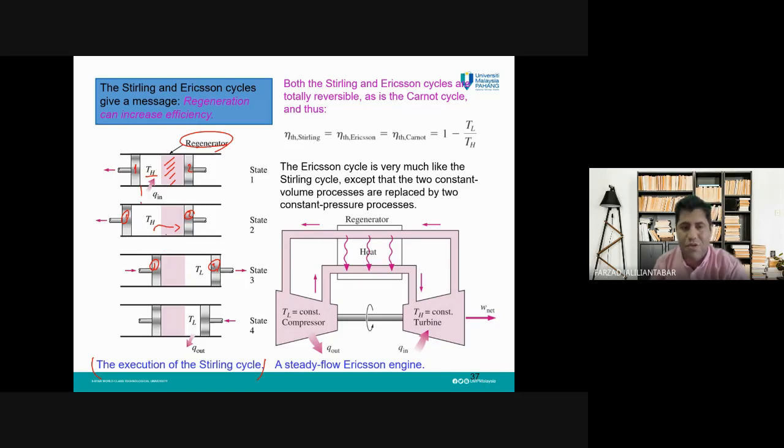During this transfer of the gas through the regenerator, if we have this in the real world, some of the thermal energy will transfer from the gas to the substance. So the temperature of the gas will drop to TL, which is the minimum, the lower temperature of the gas, and a part of the thermal energy Q is given to the regenerator. So during this shifting, we have a Q to the regenerator.